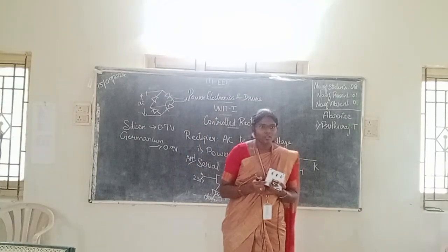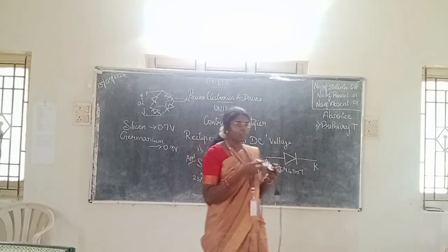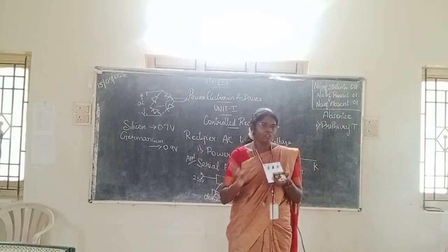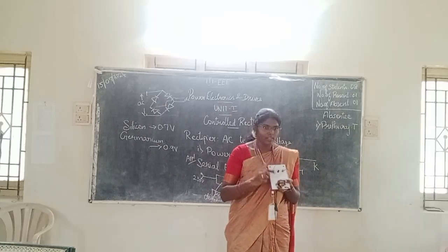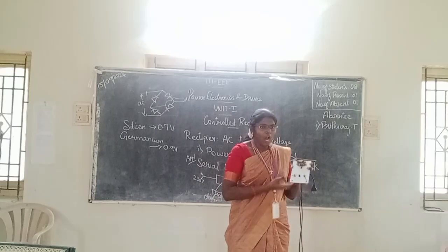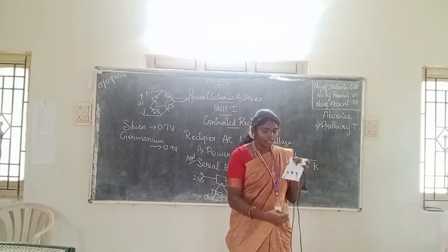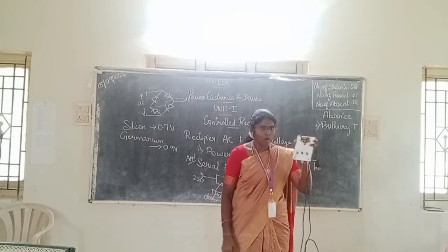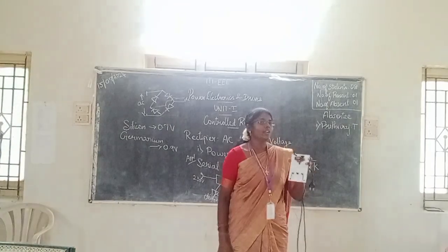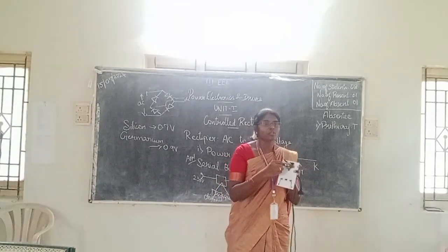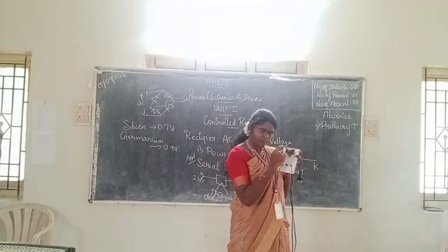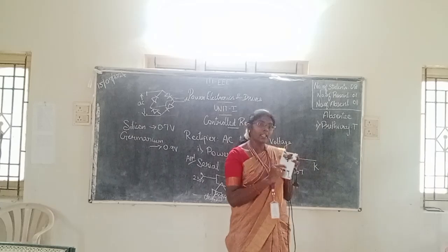It will step down. You know the concept of a step down transformer. The primary winding has more turns than the secondary winding. So based on the number of turns, it is going to transform the electrical voltage. It will step down the electrical voltage. Now here we will be getting the output from the transformer. Here the phase and neutral are AC only. We are just stepping down the AC voltage, that is from 230 volt to 9 volt. If you notice, here we have written 9 volt. So it is stepping down to 9 volt AC. Okay.